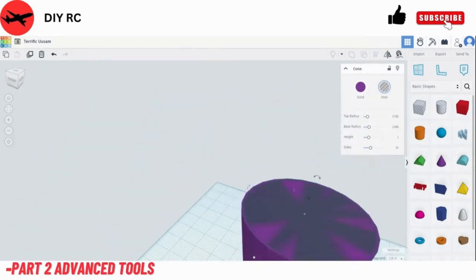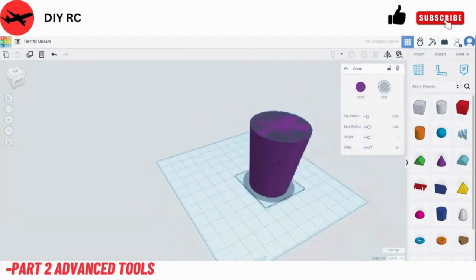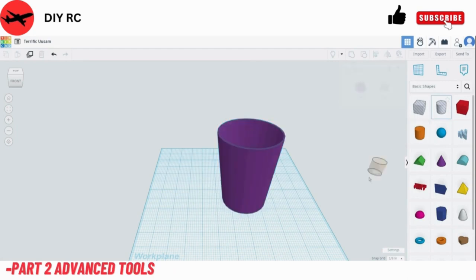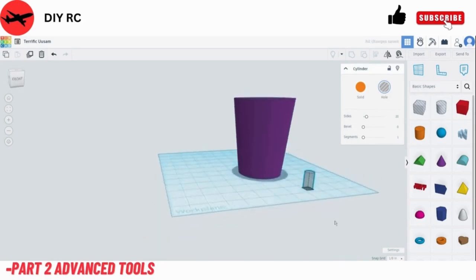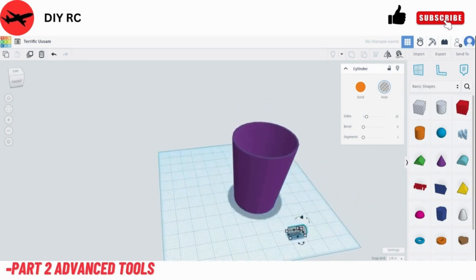so you can see there's a little bit of solid outside where the hole isn't touching, and then we're going to move up the bottom so there's a base to our cup, and then we'll highlight over the whole thing and group it together. This makes our cup. Now, because 3D prints are heavy, we're going to put some holes in it. So we're sizing our holes, and then we're going to rotate it over onto its side and put it into the middle.